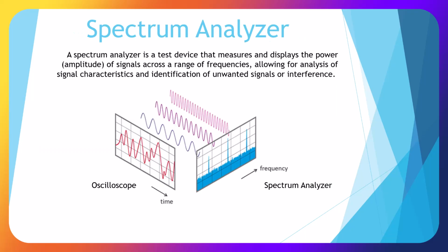Okay, let's take a look at our spectrum analyzer. As our oscilloscope looks at time versus amplitude, our spectrum analyzer is going to look at frequency versus amplitude. And it is an excellent tool for doing troubleshooting and design.